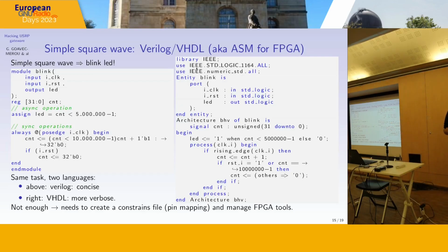It's possible to use another type, STD logic vector, but this implies some conversion just to be able to do the +1. Using unsigned, it's a positive or equal to 0 signal, and it's allowed to +1.